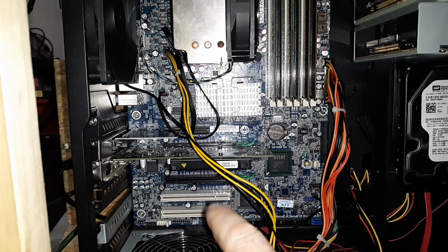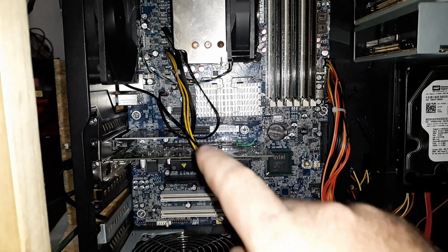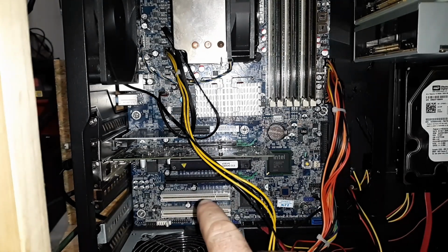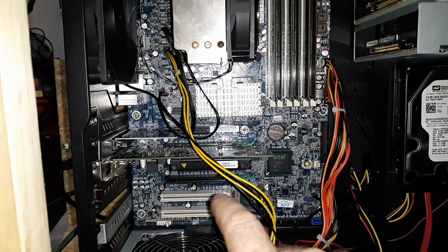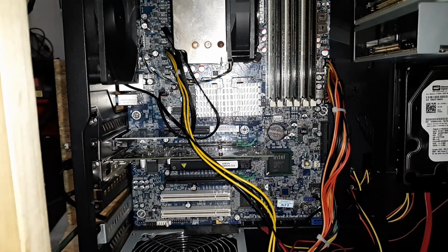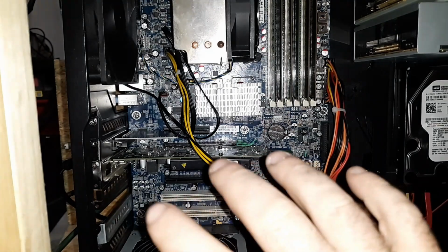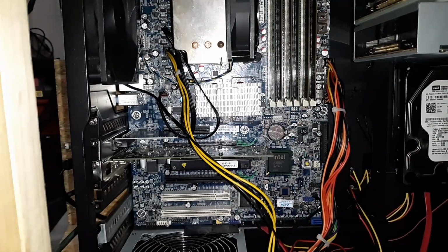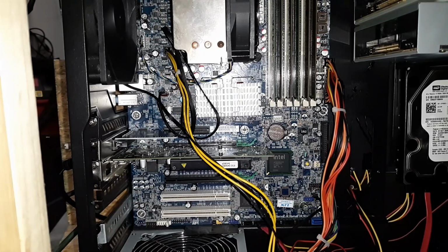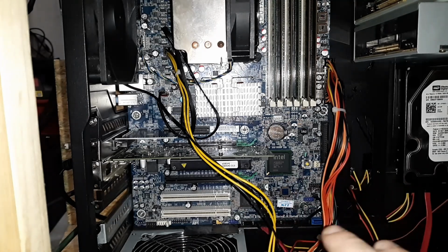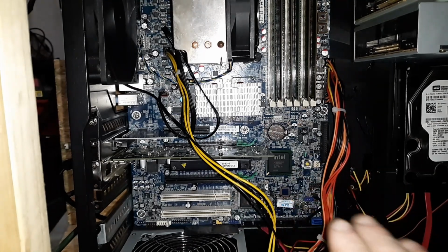So to solve the problem of everything you just saw, I need to take that PCI Express one out and use a PCI one so that I can get the 6 volts required to properly drive my 4-axis controller back there. So that is the reason that you have the one direction and why you have multiple errors and stuff. If it does run, it almost always freezes, pauses in the middle of a thing, or crashes. And people just can't understand what it is.